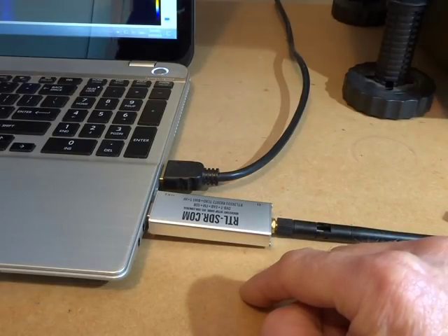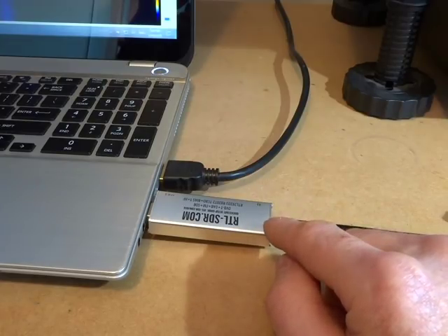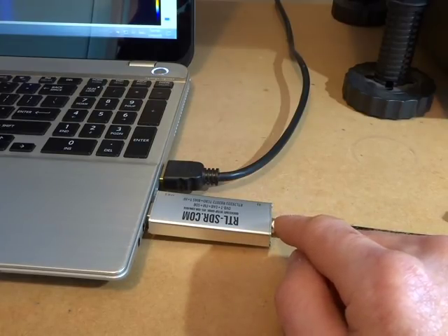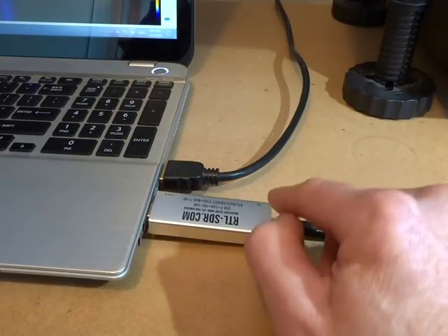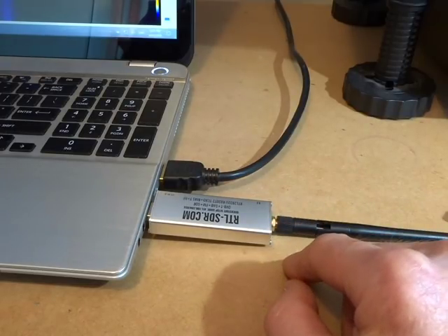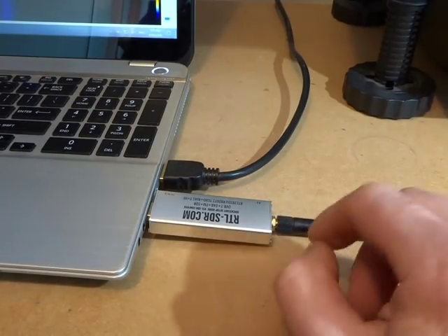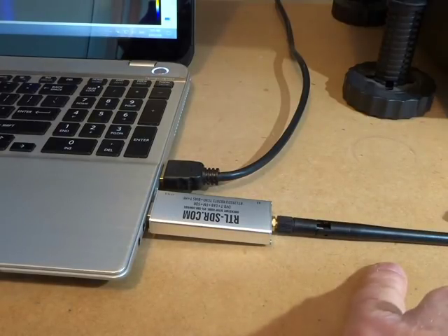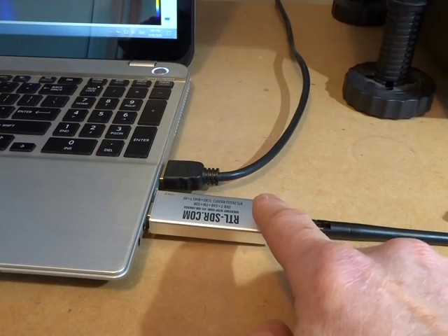In this particular case, if I tap into the quadrature output, I can actually tune SDR Sharp down into the HF region, because typically these devices, certainly the version 2 and earlier, were restricted to VHF and above. So unless you built a down converter to mix those higher frequencies down, say again the HF, and mix it up into the VHF band, you couldn't use them. But the version 3 devices are different.